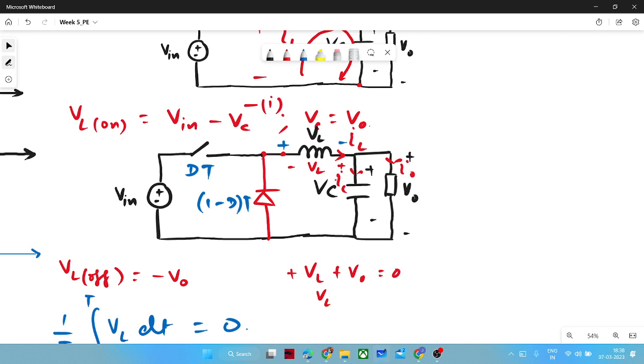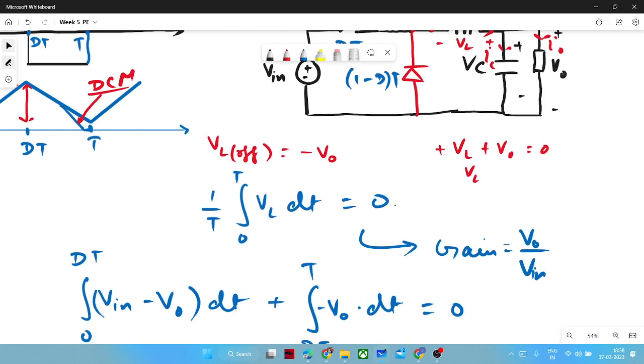The capacitor will filter all the ripple that was coming through the inductor, and due to that the capacitor will undergo charging and discharging, and after that you will have a smooth DC current at your output.